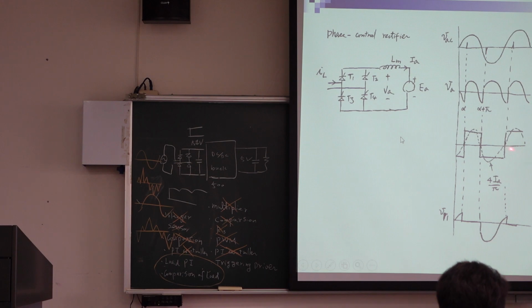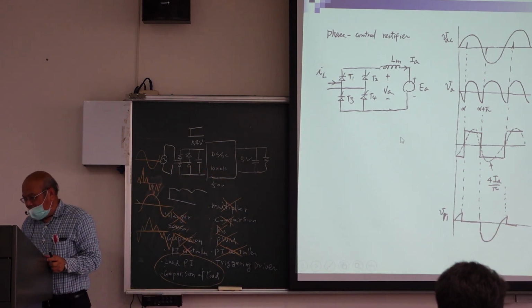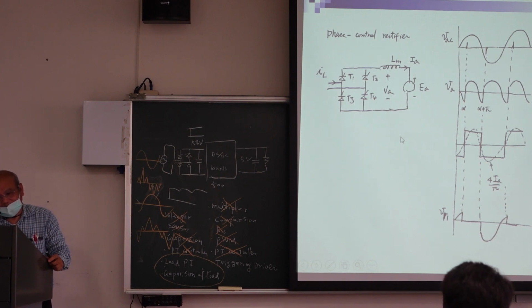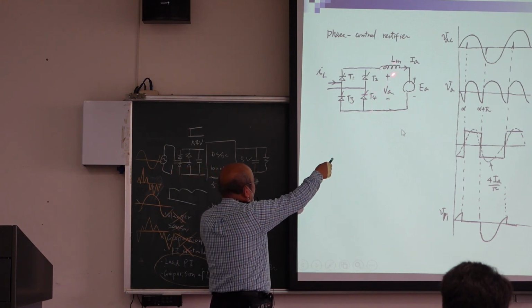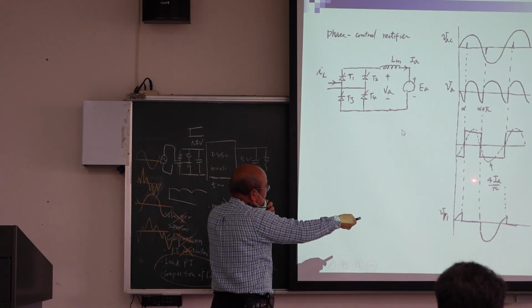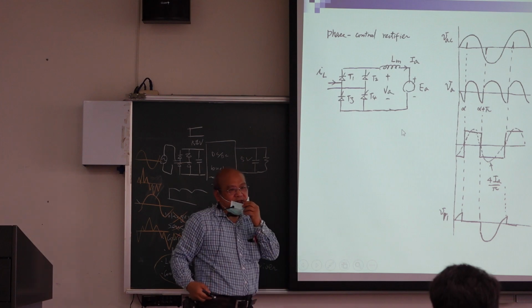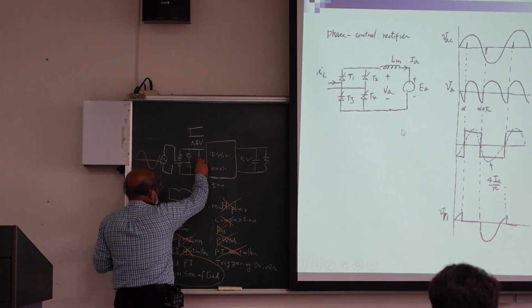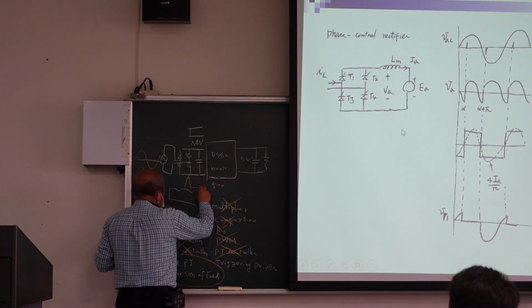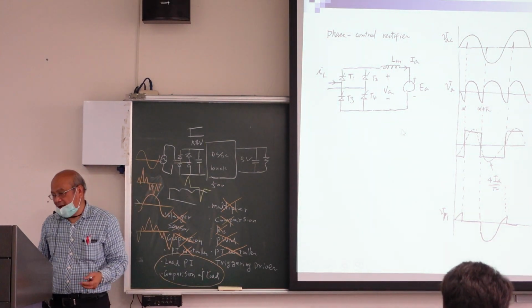So when we control the motor, the power factor is always changing. So this is phase control rectifier. So what can we do? We can use inductor to replace capacitor. Before, here we use capacitor, but now we use inductor. If we use inductor, then the current is close to sinusoidal current, then it could be better. If we use the capacitor, then the current is like this, then it is not good. But now it becomes square wave, right? It is better.